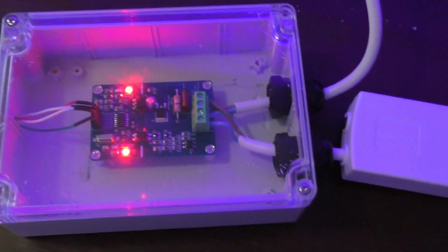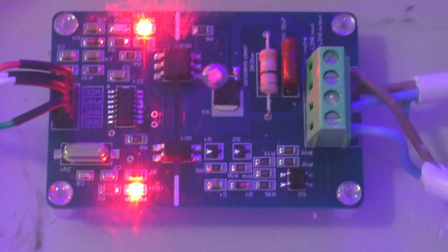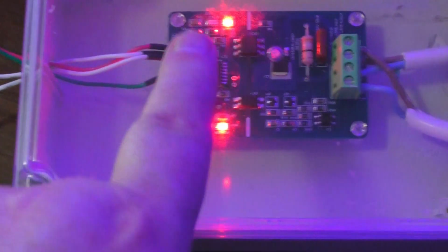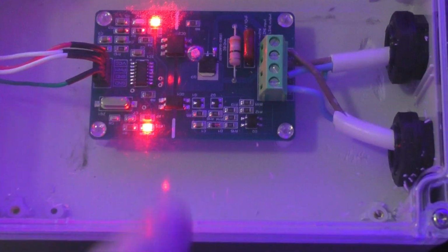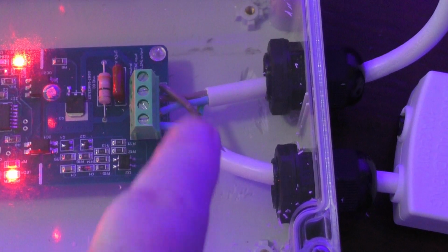Now this is the bit you need to be careful of. I can get that properly filmed. This is the board, the TRIAC board. The good thing about it is the high power and the low power part is separate. So the low power is over here. That's the input from the micro. All you need is PWM and the power supply really and the ground. And this is the dangerous bit where you don't want to be touching.